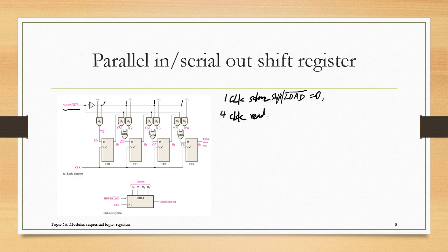we have logic 1 to gates G1, G2, G3, and G4, right? If we recall the property of the AND gate, if one input is 1, then the output Y1 will totally depend on D0. So Y2 will be D1, Y3 D2, Y4 D3. Sorry, for D3.